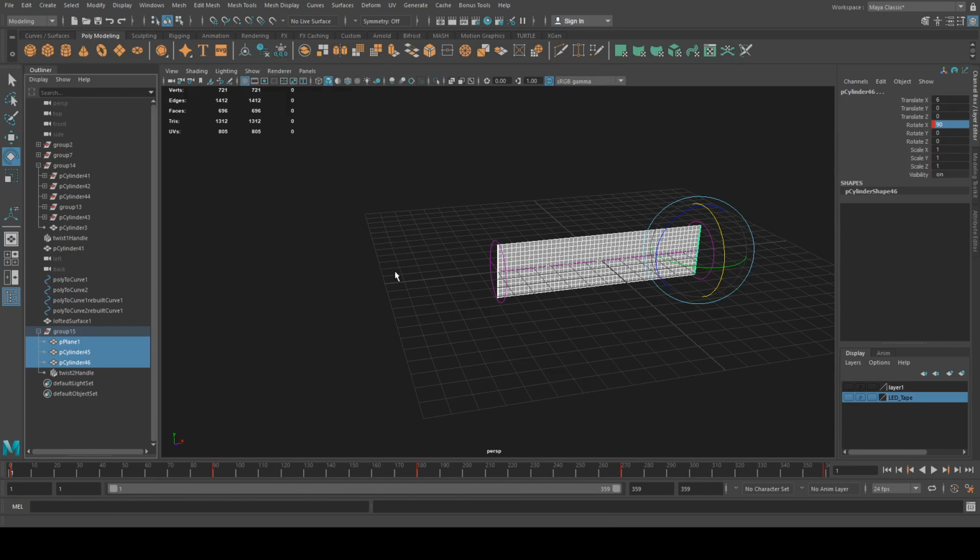And I've added ABC export and ABC import as plugins to Maya to be able to export an alembic file. So now I go to cache alembic, and I go to export selection to alembic. I'm going to do the time slider because I want from 1 to 359 as my range. I don't put anything else in this because D3 is actually quite simple as far as alembic, and it only allows you to really bring a polygon mesh with a UV that's been animated.